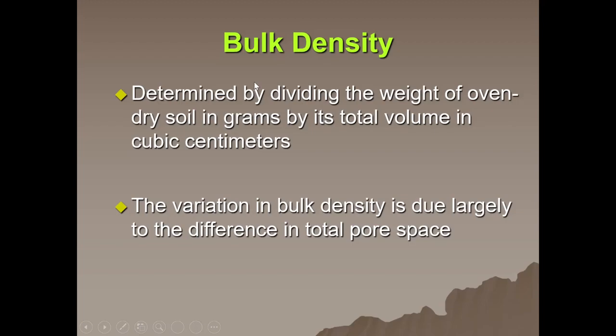But bulk density generally does not go like 30, 40, 10 and so on. The ideal bulk density for soil is 1.33 gram per cm cube. Again, 1.33 gram per cm cube is the normal or ideal soil bulk density. When the bulk density is too high, for example 1.6, the number does not sound like a very big number, but 1.6 is a very high bulk density. Once the bulk density is very high, then plant roots will have a hard time to penetrate the soil.